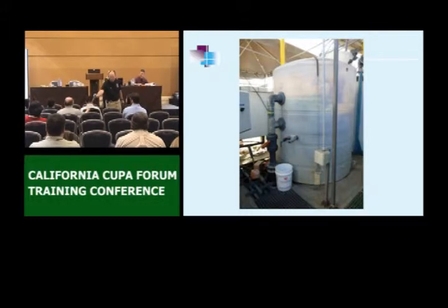Make your comment again, please? The secondary containment will be based on the largest container within the secondary containment. If all of the containers break at the same time because of an earthquake where the hard plumbing breaks, we're going to get a possible release from all of the tanks, which is going to be greater than the total volume of the secondary containment, what it's able to hold. That's a distinct possibility.